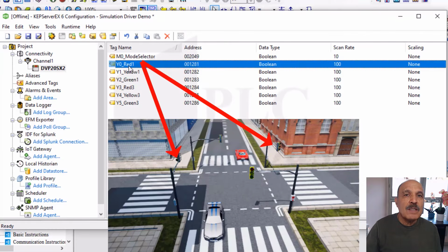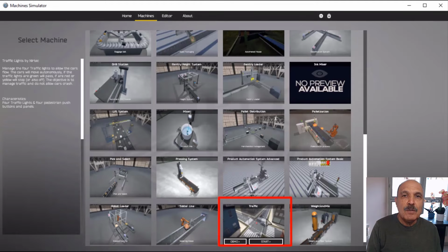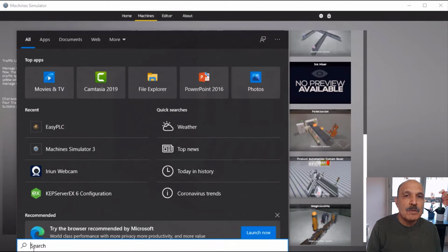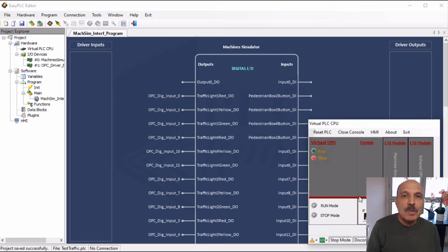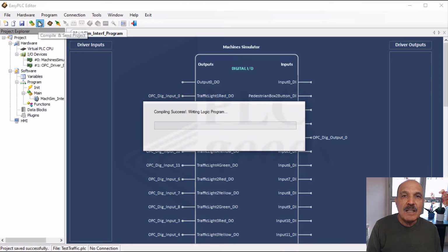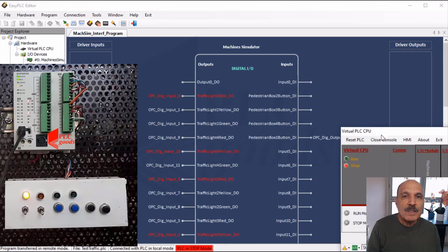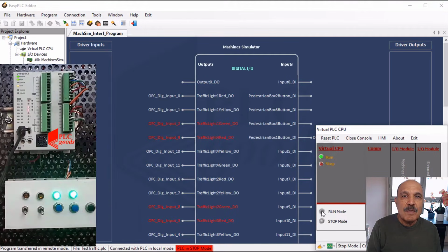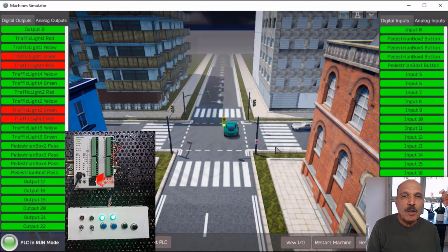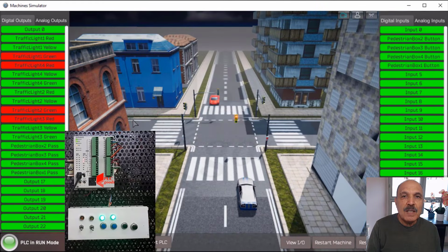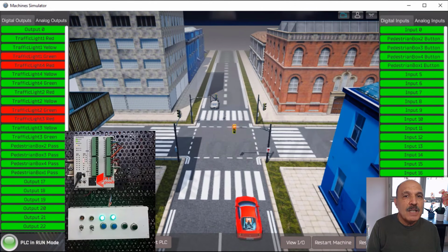The video guides us through creating a traffic light project with normal and flickering modes. We use counters to toggle between these modes and design a detailed program with symbols for light control, timers, and comparisons for state management. The tutorial shows connecting to an OPC server through the Delta PLC and then simulating the